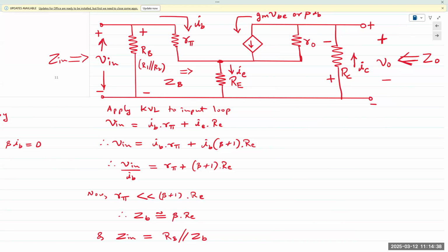So if you want to make an approximation, remember at the beginning I said you can have multiple pathways you can derive. One is by finding the impedances and then taking the ratio of the impedances. The other way is if you write expressions by eliminating variables, we can write expressions for VO. And then in the equation for VO, we can incorporate VIN. Then we can take a ratio of VO over VIN. So anytime you're faced with any kind of circuit, different kinds of biasing circuits would result in different kinds of equations. But if you proceed with these steps, you'd be able to analyze and find the voltages, the currents, the voltage gain for the amplifier circuit.